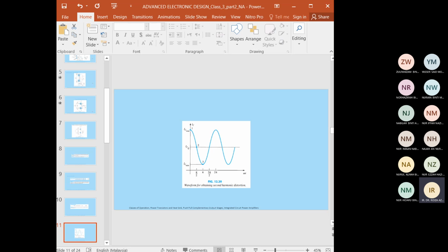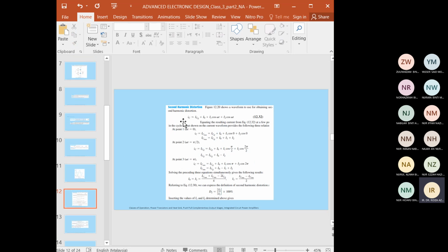So the current waveform contains the quiescent current denoted by ICQ, which occurs with zero input signal, and an additional DC current denoted as I0. It is the non-zero average of the distorted signal. The fundamental component of the distorted AC signal is denoted by I1, and the second harmonic component I2 is at twice the fundamental frequency. Okay, so the other harmonics are also involved in this equation: IC approximately ICQ plus I0 plus I1 cos omega t plus I2 cos 2 omega t.